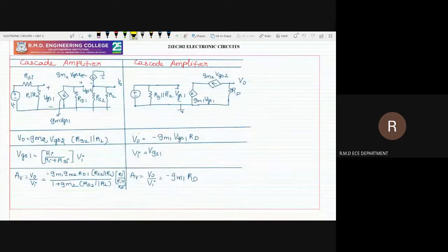Then I have to analyze in the small signal AC equivalent diagram. You have to redraw your main diagram into this small signal hybrid-pi equivalent model. Here, the voltage source in series with the resistor and the two resistors in parallel, we call it RTH. And it is an NMOS transistor, with plus for the gate symbol and a minus for the source symbol. For the first M1 transistor, we call it gm VGS1, and for the second current source, we call it gm VGS2. The gate and source symbols, in the same way, both are NMOS only, connected like that.